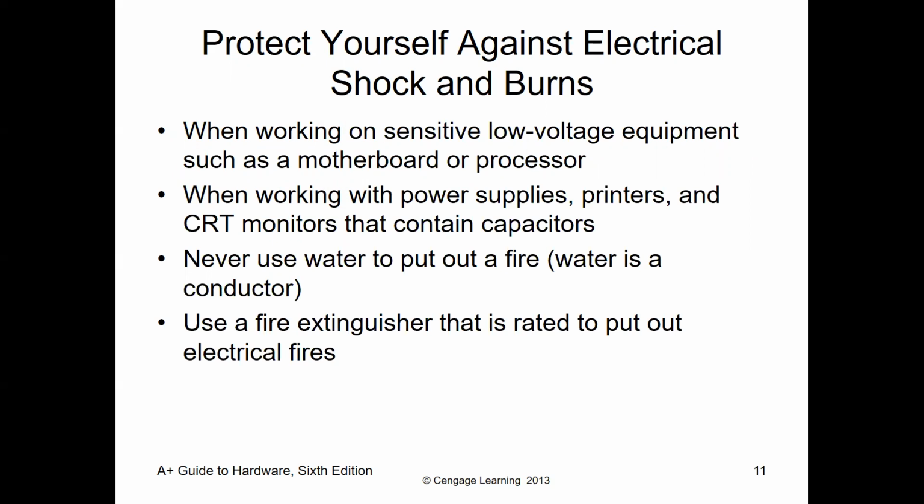Protecting against electrical shock and burns, continued. When working on sensitive low voltage equipment, such as a motherboard or processor, ground yourself with an anti-static grounding bracelet connected to a ground. When working with power supplies, printers, and CRT monitors that contain capacitors, do not ground yourself, because power can flow through you to the ground and you may get shocked. Power supplies and monitors are considered field replaceable units, which means you are expected to know how to replace them, not repair them.